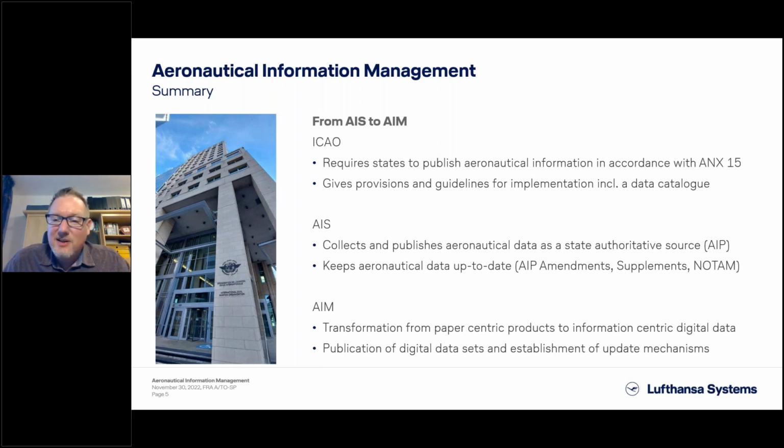So AIS will code the data according to the data model and bring the data to the end user using SWIM services. They will provide the data using the services. And of course, AIS still has to take care that aeronautical data is always up to date. And as I said before, supplements and NOTAMs can be replaced by OPREP in the future.